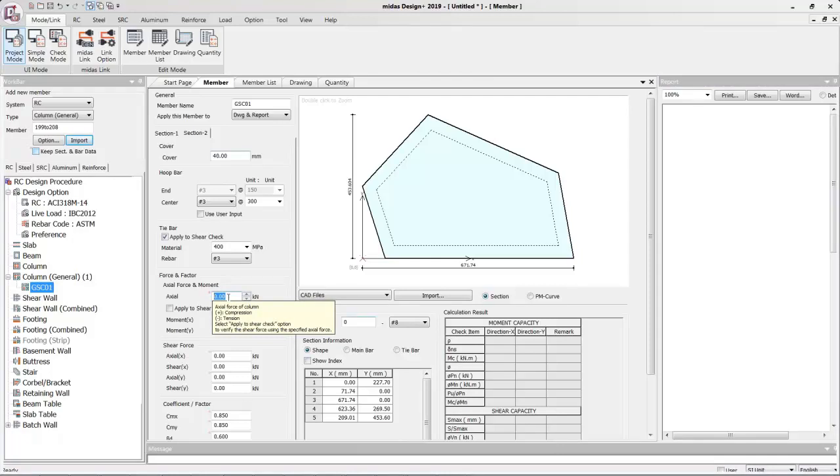Alright, so that we will, let's take it as 3656. I've taken this load value from one of the gen files. Then further we can put this actual force for the shear check. Then the moment, this is going to be strong axis as in major axis moment, and this is the minor axis moment, mx and my.